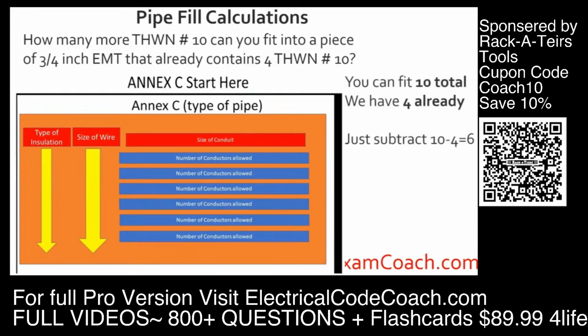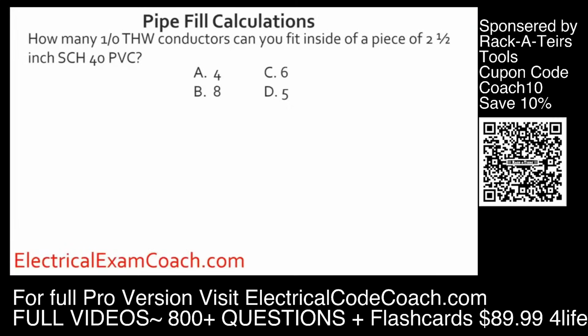And we find out that we can fit 10 originally, but our question states that we already have 4 of them in the pipe. So all we have to do is do a little 3rd grade math. We take 10 minus 4 equals 6, and we find out that we can fit 6 more inside of this conduit. Great job. How many 1/0 THW conductors can you fit inside of a piece of 2.5 inch Schedule 40 PVC?